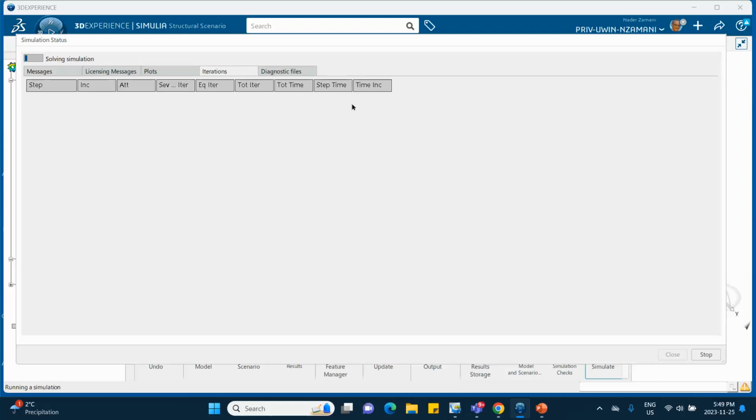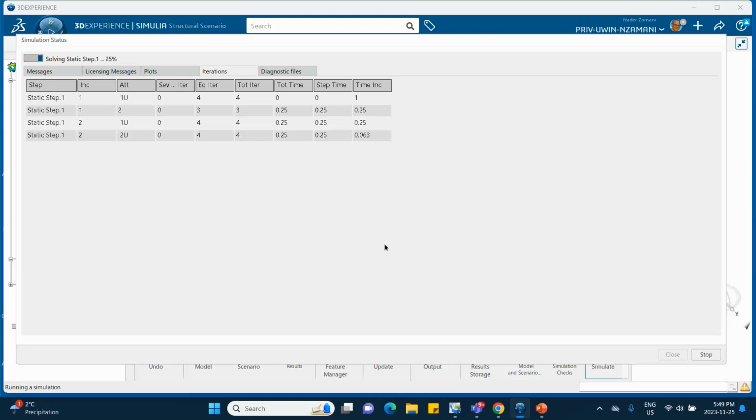Okay, so it's going to do the iteration, and I can tell you that when it reaches some point, before I get the 0.5 millimeter displacement, it actually stops, and that's where it detects the buckle. Let's move on. It's going to be very fast. If things don't work out, we can go and change the numbers there. It looks like it's chugging along.